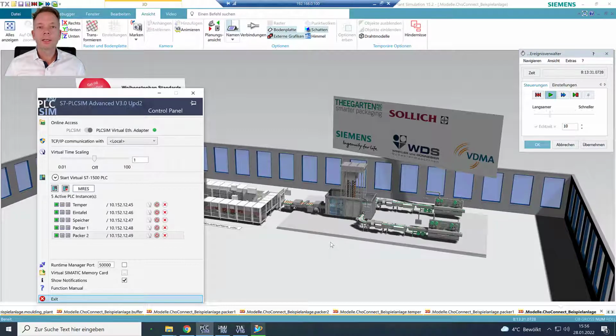To realize the WS Suites interface based on the OPC/UA companion specification for Weihenstephan Standards, OPC/UA servers have been implemented on all of those controllers. To do this, you use the standard OPC/UA server functionality, in this case provided by Siemens, but of course this could also be controllers from other companies, Allen Bradley, Schneider, etc. Many others also provide OPC/UA server functionality already.